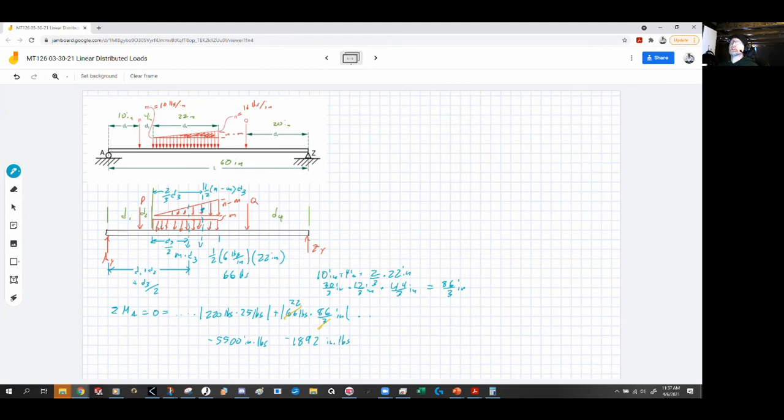Notice how this set of units is pounds per inch, and we end up instead with pounds times inches, okay? That's okay. I made sure that I kept those units straight all the way through. I've seen students all the time just start throwing in pounds per inch. That means you divided. That means the units are actually, one is divided by the other. And that is not the same as pounds times inches. That means they're actually multiplied. If you divided rather than multiplied, you didn't do it right. So make sure you use the proper units every step of the way.